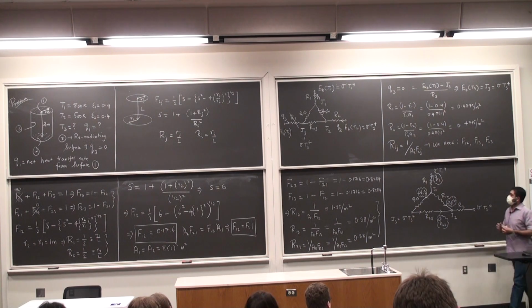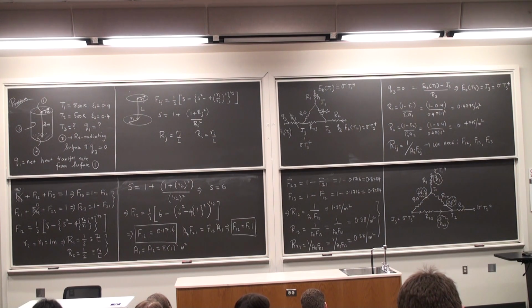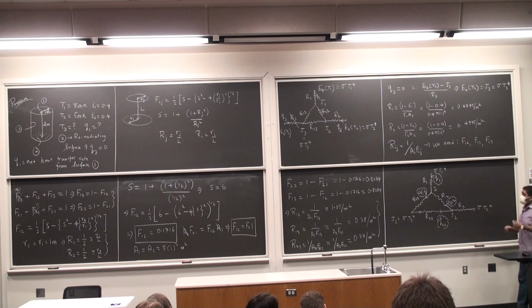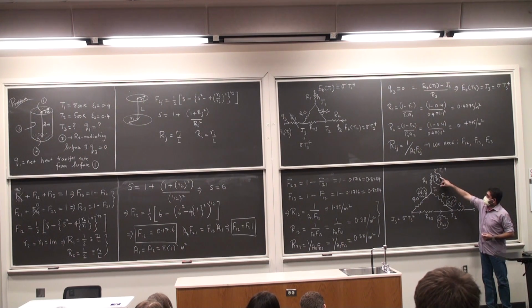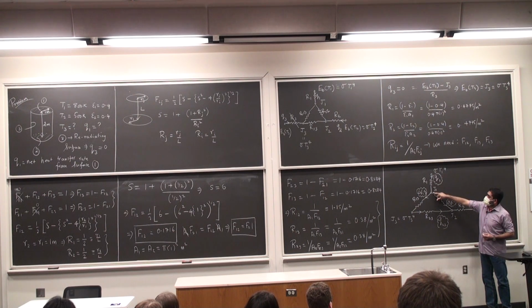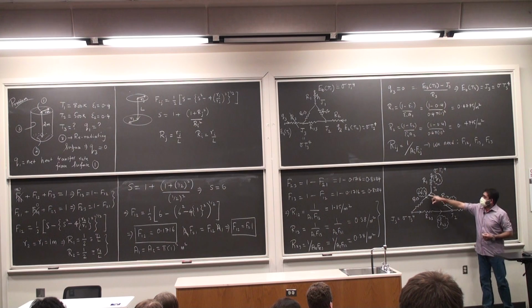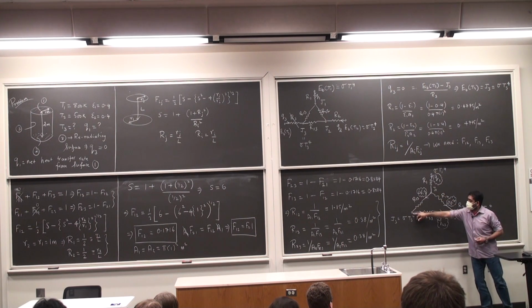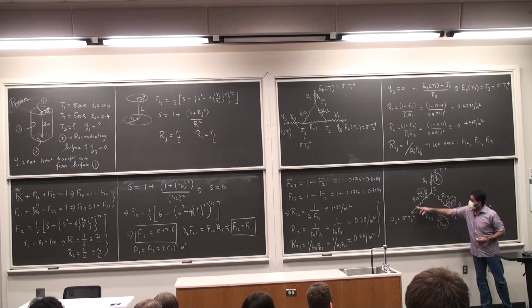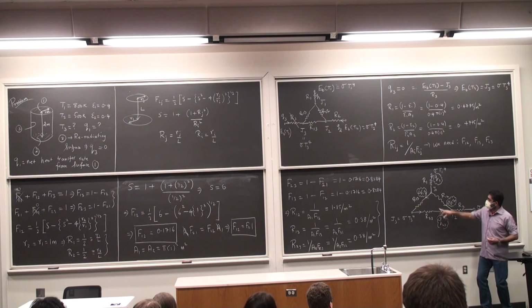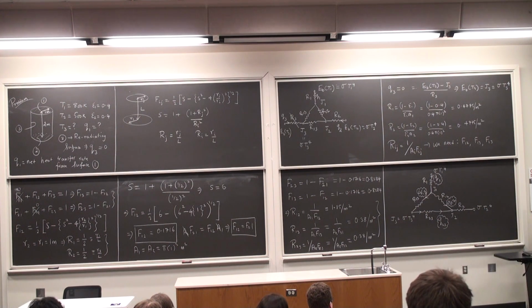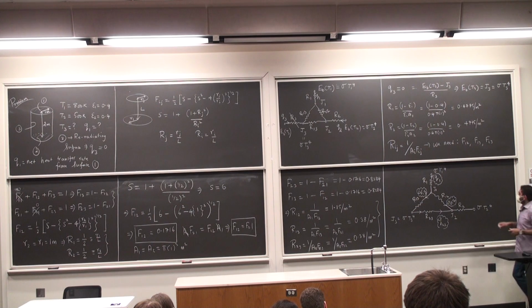And you see now we can translate this into a nice resistance network by saying, okay, current starts by flowing into this node as Q1, flowing through this node as Q1, comes to this junction here, it splits into two branches. Watch this. This current will come to this node, but there is nothing going on there, so the same current will flow through here as well. So Q23 is the same as Q13, which means that those two resistances are in series.